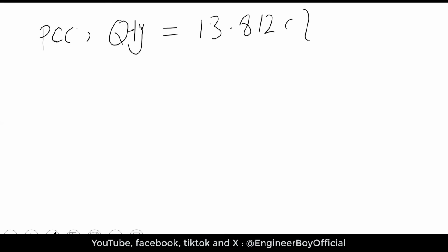Yes, sir. Now next, this is how we can do material analysis for the brick work. Let's do it for the PCC work. We will take the same room which we have calculated, and let's say that is 13.812 CFT. It was just calculated, the PCC work. Now the ratio for this, if you remember, it was in the foundation, and I think it was 3 inches, so you have to confirm that, no problem. It was, I think, 1:3:6 ratio.